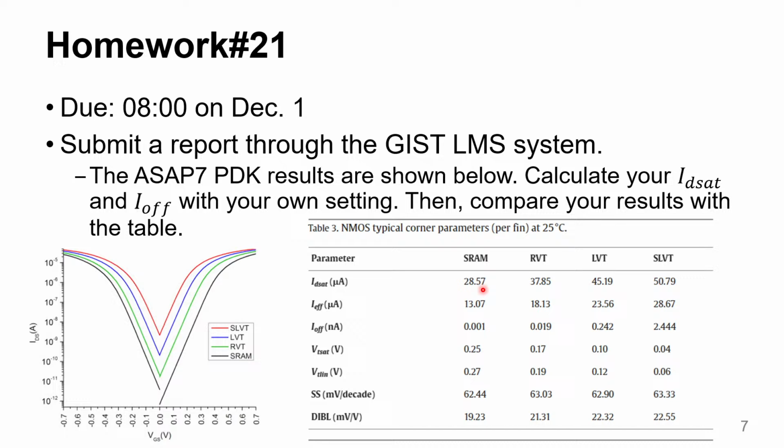So maybe you can think that, oh, we have reduced off current more than 2000 times, so about 40% reduction of on current is much smaller than this 2000. However, please note that we must consider the subthreshold current or off current in a logarithmic way, but in this on current case, a few percent difference does matter, so we cannot live with this kind of huge reduction in general.